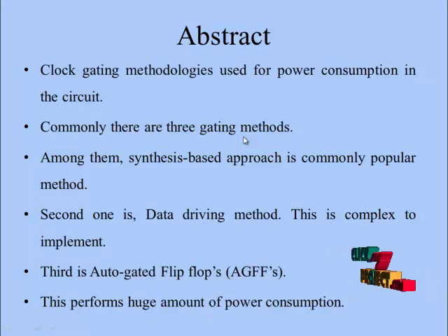Flip-flops are the basic storage elements used extensively in all kinds of digital designs. In particular, digital designs nowadays often adopt intense pipelining techniques and employ many flip-flop-rich modules such as register files, shift registers, and first-in, first-out memories. It is also estimated that the power consumption of the clock system, which consists of the clock distribution networks and storage elements, is as high as 50% of the total system power. Flip-flops thus contribute a significant portion of the chip area and power consumption to the overall system design.